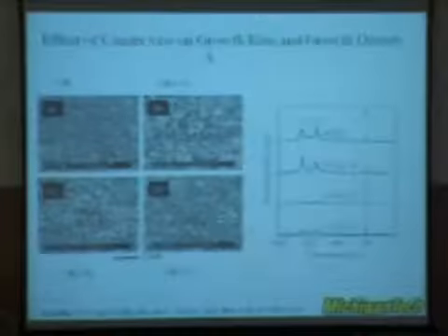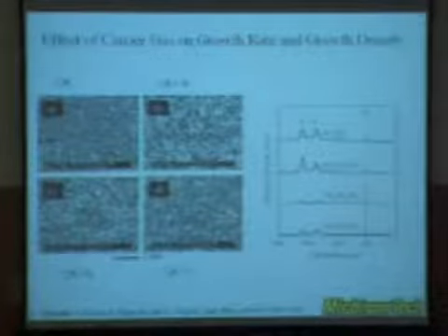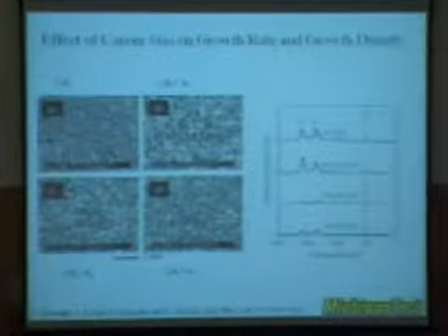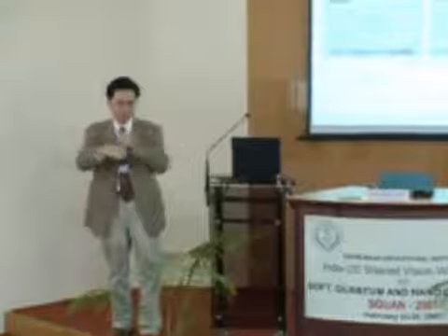By understanding this technique, we are already able to control the so-called density of the tubes. What is important for the most effective growth is that you have to make sure that all the catalysts, it might be 1 trillion pieces of the catalyst at this size on the chip, will be effectively grown. So that when they try to move randomly in various directions, they will knock into each other by van der Waals force. Around every nanotube there are many tubes that will try to knock on it. So the only way that it can escape is going up, right?